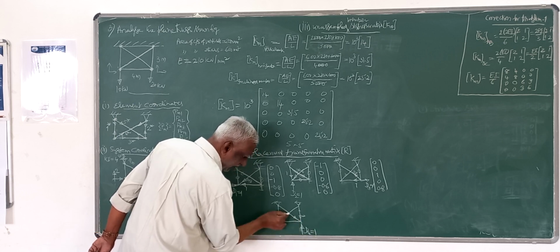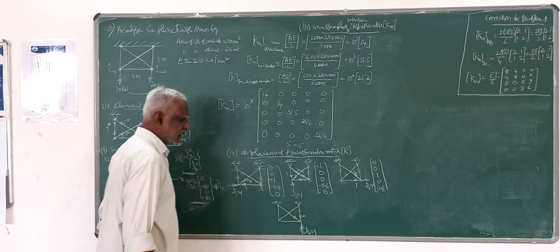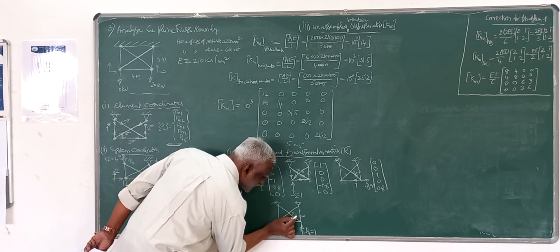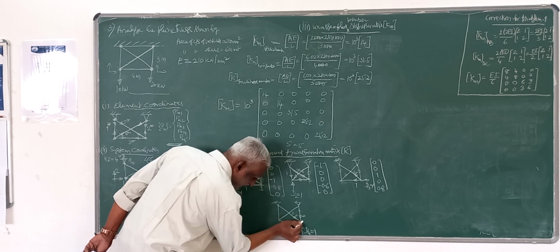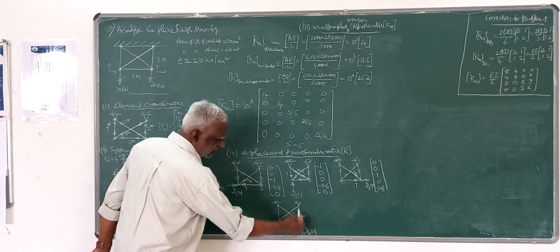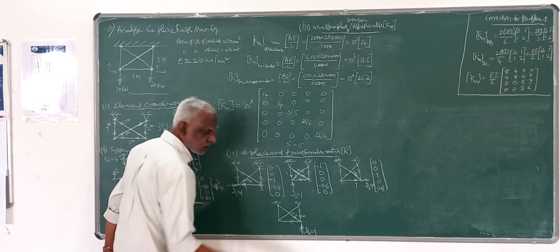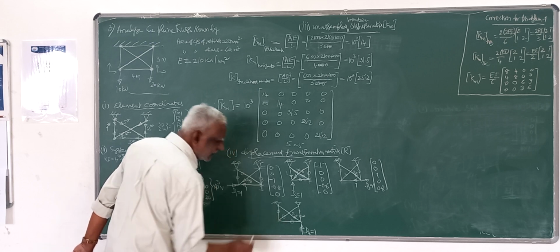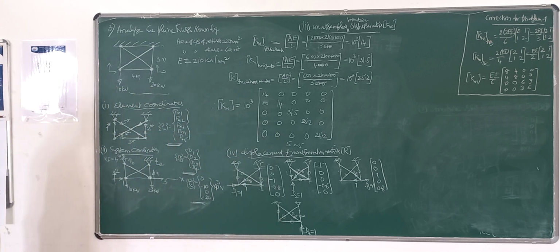So this is nothing but the vertical component, sine means it is sin theta, it is 0.6. So here it is a horizontal member, it is 0. So where the displacement is given, only these three are affected and other members automatically won't have any displacement and it has to be 0.